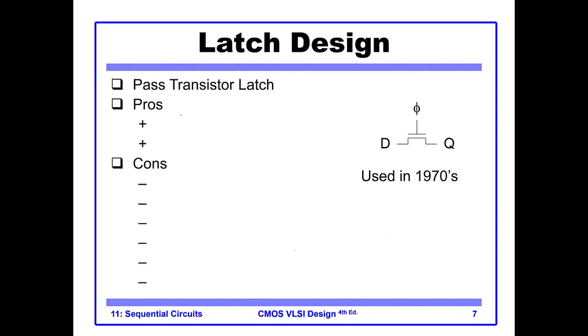So we discussed the design of a latch using a mux in the previous lecture, which was this design where you have on the zero a feedback path, and then you have this clock or gate signal, and this is our Q, this is our Q prime. So that is a D latch. Let's discuss some other ways quickly in which we can design the D latch.